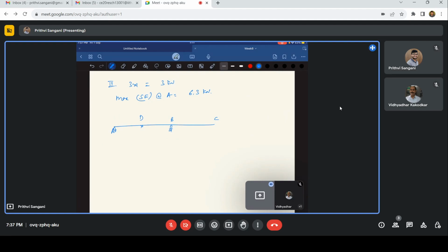What I'll try to do, like we said earlier, is remove the support at B and lift it up, and see what the deformed shape of the beam is. So I'll remove this and lift it up. What happens? This is a free support. It simply lifts along with it, and it will rotate here.